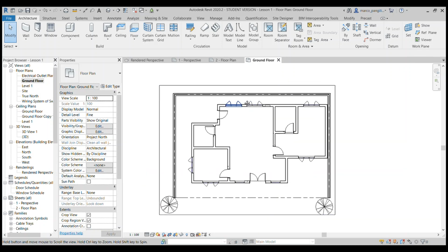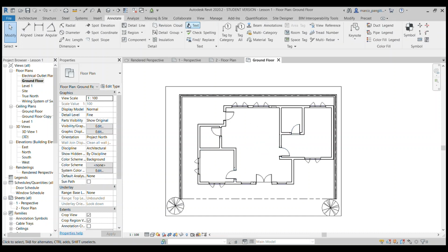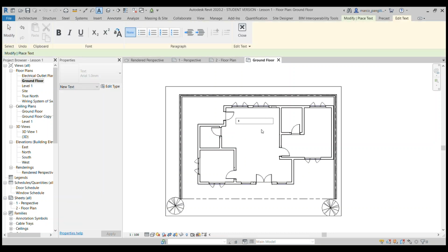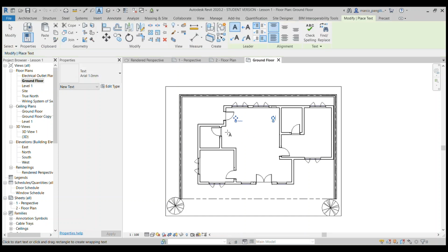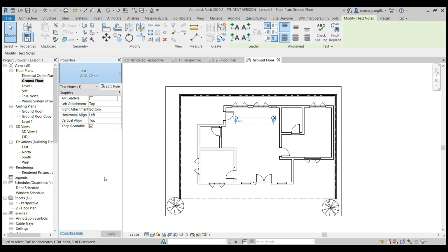So now guys, gusto kong ilagay na natin to sa ating sheet. So before that, gusto ko syempre ilagay natin ang pangalan kung ano ba yung mga division na ginawa natin sa ating floor plan. So by clicking annotate and just putting text, halimbawa this would be our kitchen. So yes, keep that message and then change it to 6 mm. Change this.